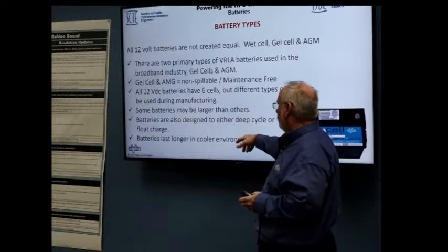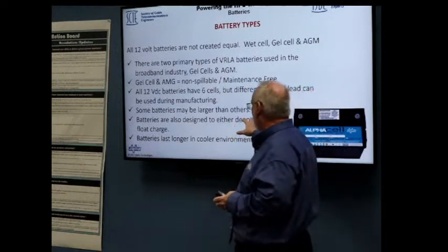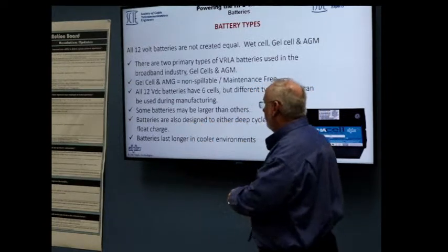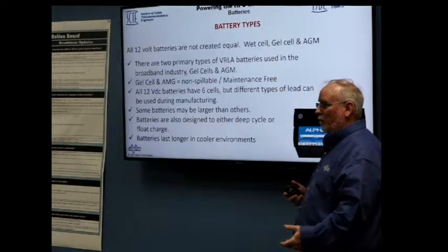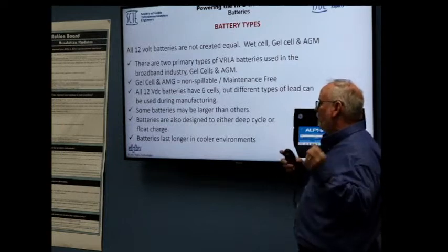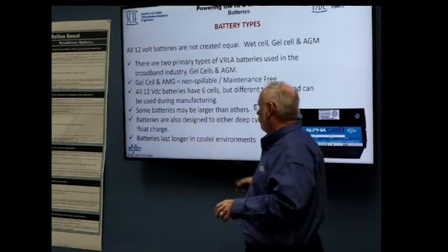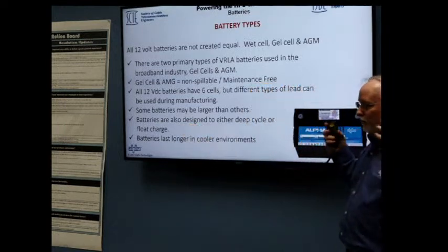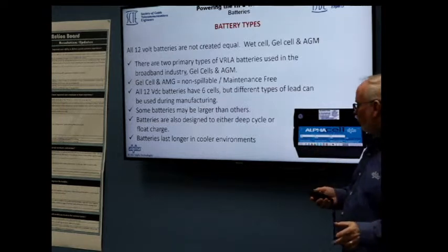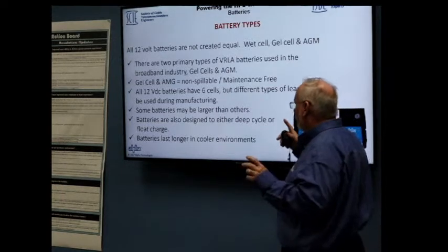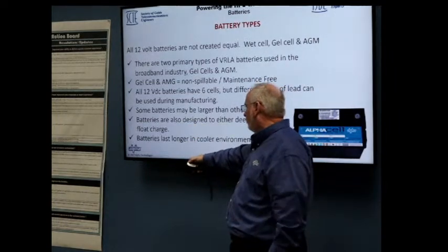Some batteries may be larger than others. Some may be designed for deep cycle or float discharge. Some batteries are designed to be cycled, like a renewable energy battery, but it may not have the efficiency that a regular battery does. Other batteries are designed to be in a float mode, which means I'm here, I'm ready to take a discharge. But if you do that to me every day, I'm going to fail on you. So you have to make sure your battery's the right design. To be honest, we're a standby, so a float charge is perfect for us.